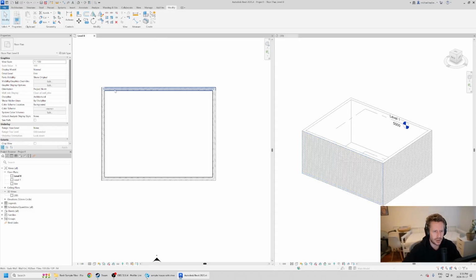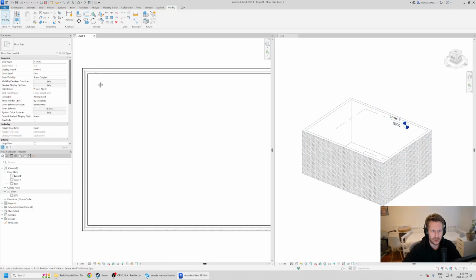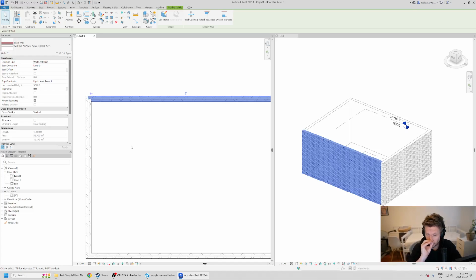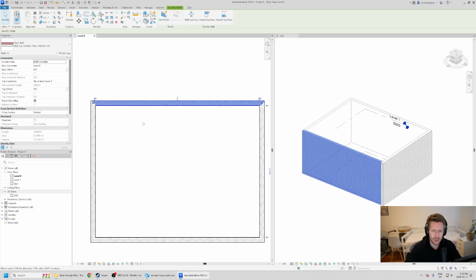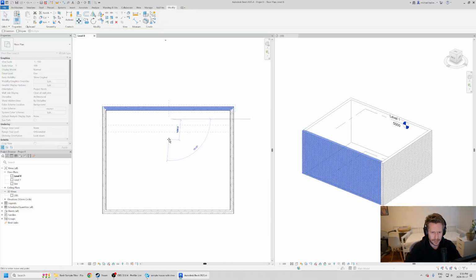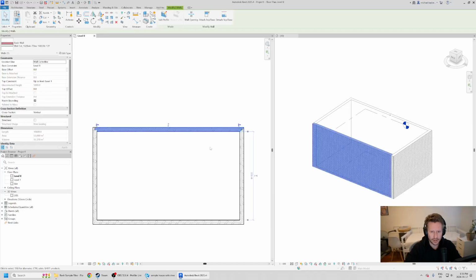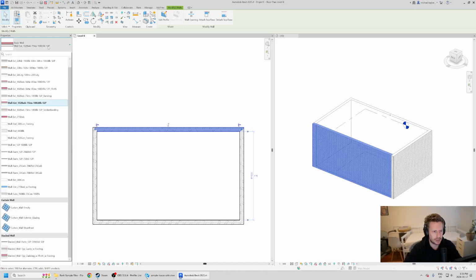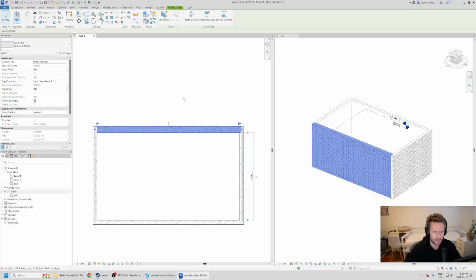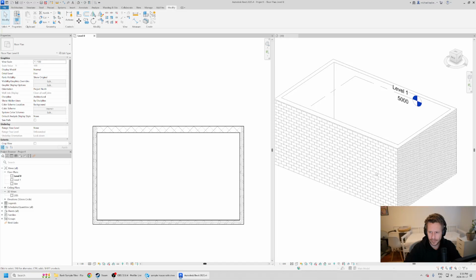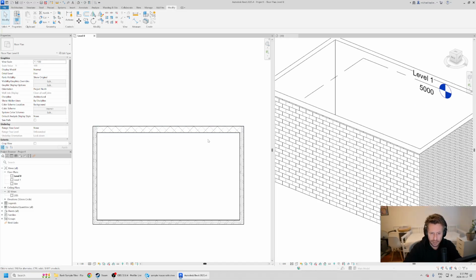The last thing I should probably touch on is changing the walls. Remember that we never really have to start from scratch, per se. It's up to you if you want to. But say for whatever reason you wanted to change the wall type here from brick to something else. Instead of redrawing it, we can just select it, come up here to what's called the type selector, click the type selector down, and say we want this to be, let's do something that's clearly visibly different. Let's just do concrete, right? This is a block wall, but that's okay. So block wall, and now we can see that everything has been modified, right?